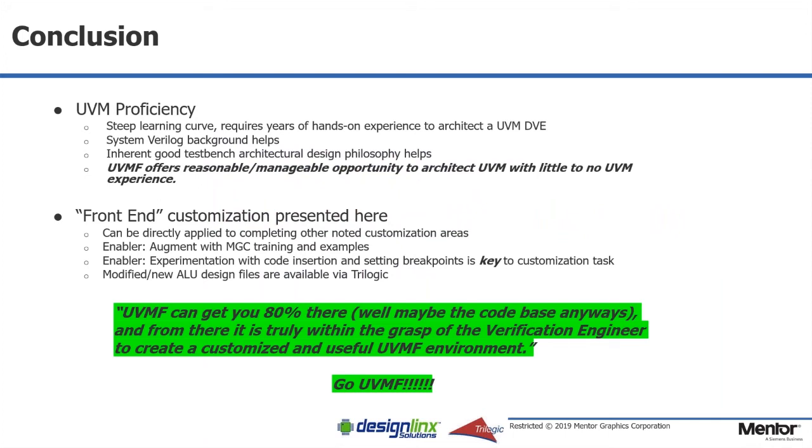In conclusion, UVM proficiency is a very steep learning curve. It usually requires many years of experience to be able to architect a UVM DVE. It really helps to have a SystemVerilog background and inherent good test bench and design philosophy. But in the end, UVMF offers a reasonable, manageable opportunity to architect UVM with little to no UVM experience.